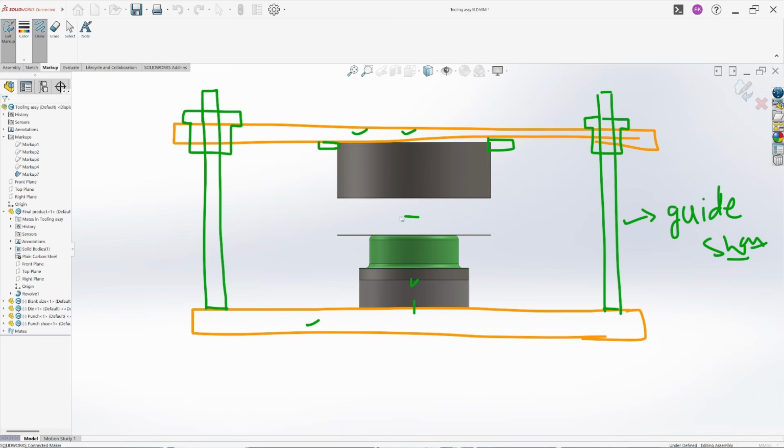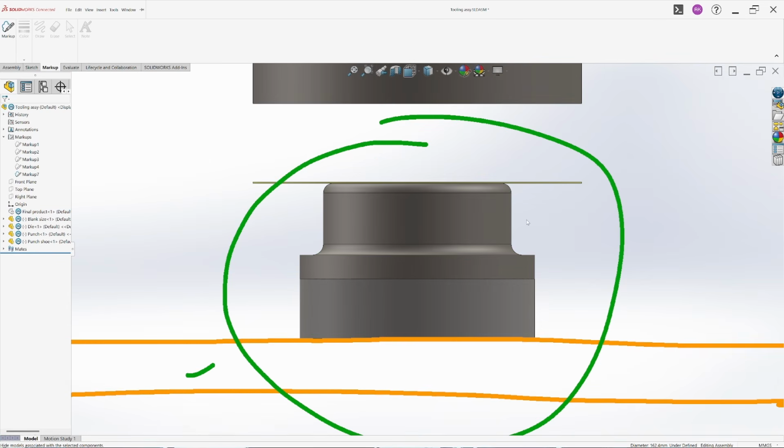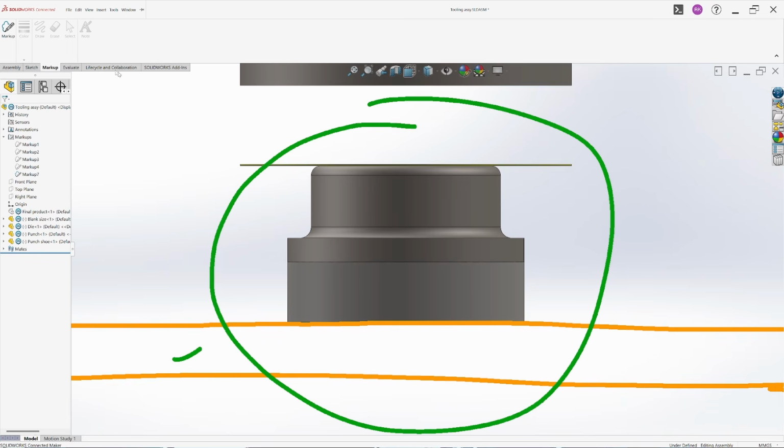Okay, so let's first try to fix our punch and this punch spacer with the base plate. Let me hide this component for a moment. First I have to mount our punch with this spacer, and for that we can use a counterbore hole right here on the punch, and make a threaded hole in our spacer, something like this. We can mount this with only a single bolt, and it will be very easy to assemble and disassemble.